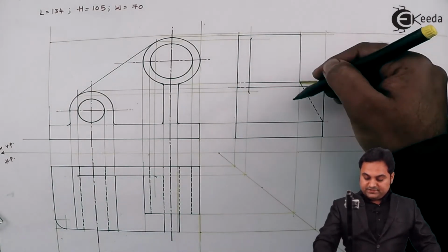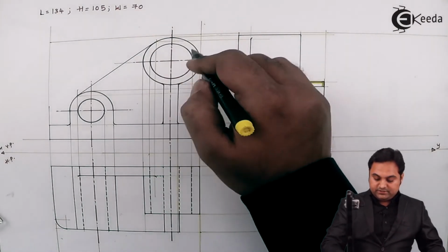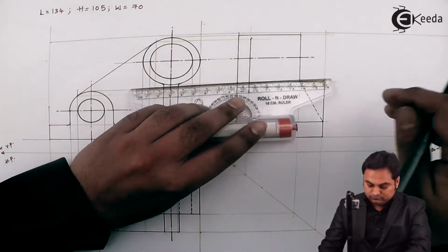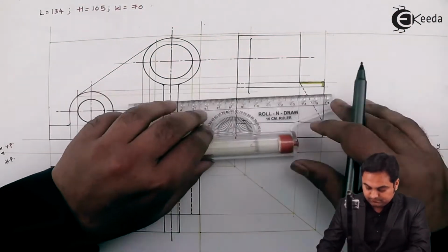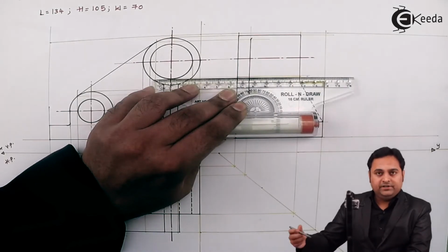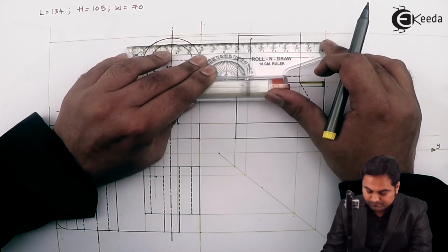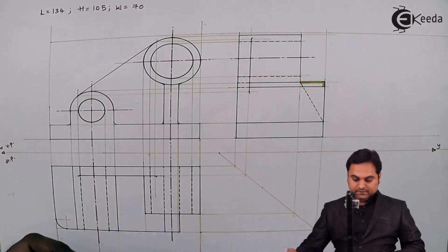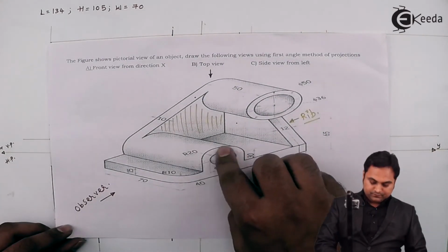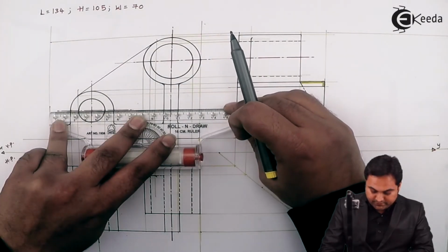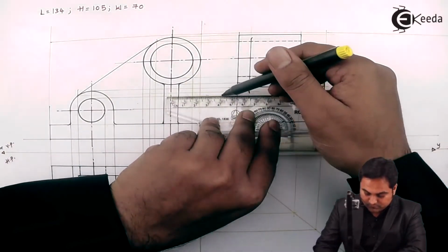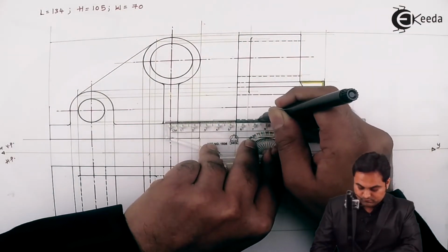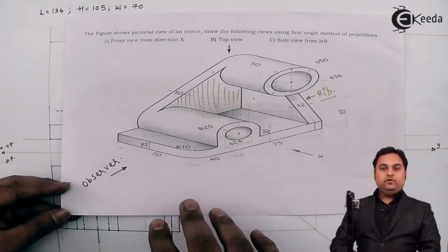Then after this, inside both the circular and semicircular part, there are hidden circles which won't be visible from the side. So projecting them, first getting their center. Projecting it light. Drawing hidden line here. Next, drawing this circle which will be hidden. When we are looking as an observer from the left hand side, this inner circle won't be visible, so it will be hidden. Getting its center first. Drawing the center line. So this will be the hidden circle. Here we complete the side view also for this figure.